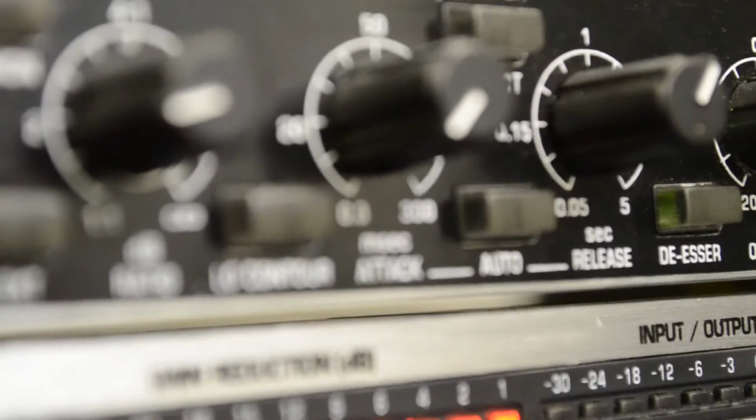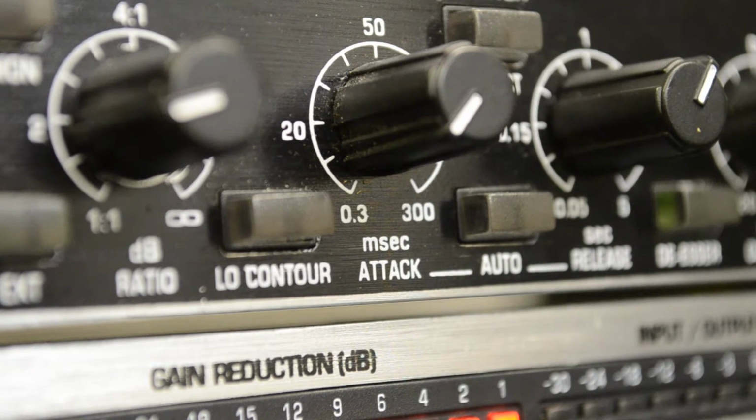As well as the threshold and ratio controls, a compressor has a number of other parameters that can be altered. The first of these is the attack. This is the time taken for a compressor to respond to a signal that exceeds the threshold. A short attack time will mean that the compression will kick in as soon as the level exceeds the threshold, and the whole signal will be compressed. A longer attack time will mean that the compressor will take longer to kick in, therefore the very start of the signal will be uncompressed.